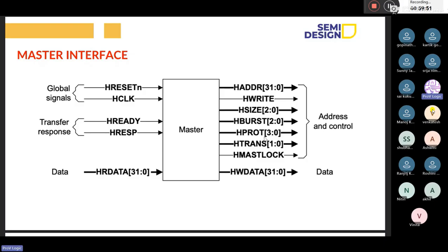Okay, and HWRITE. HWRITE means same as in the APB protocol. In the APB protocol we have PWRITE to select whether it is a write data operation or a read operation. For that purpose, HWRITE we have.